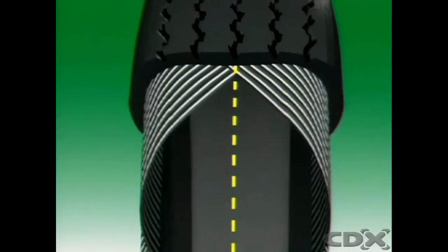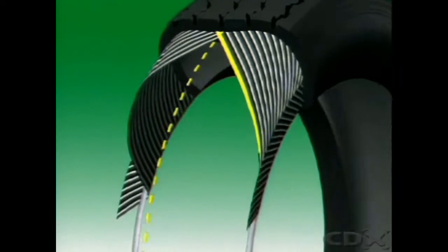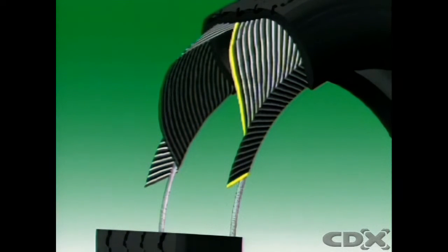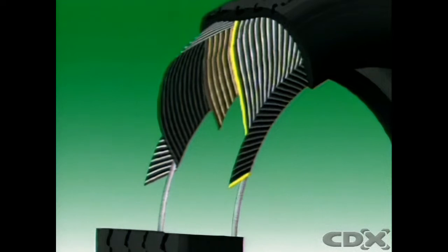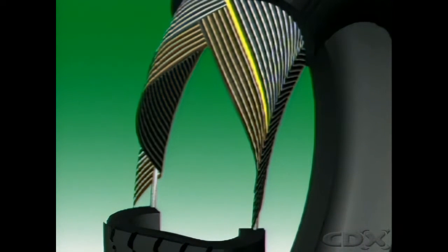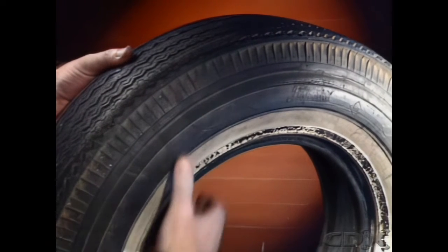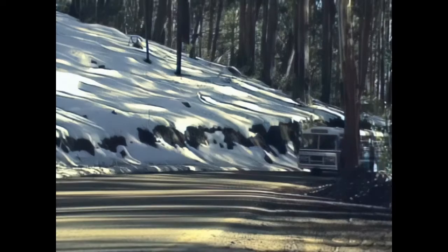The rubber-encased cords run at an angle of between 30 and 38 degrees to the centre line, with each cord wrapped around the beads. A latticed criss-cross structure is formed, with alternate layers crossing over each other and laid with the cord angles in opposite directions. This provides a strong, stable casing with relatively stiff sidewalls.